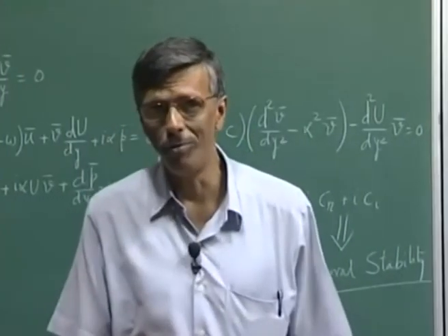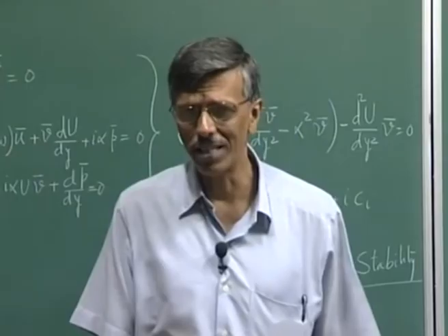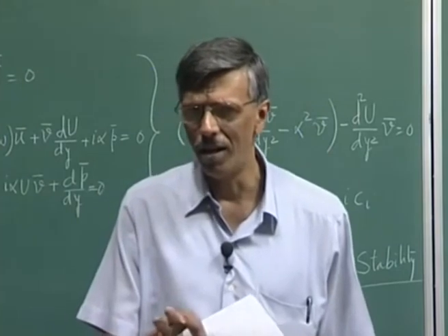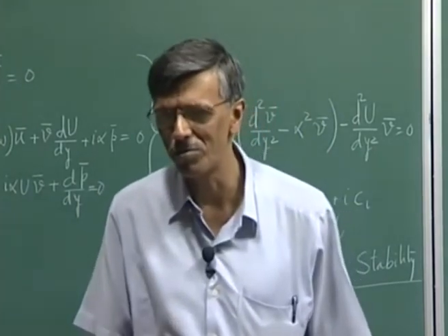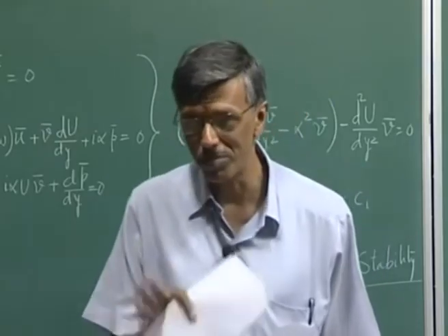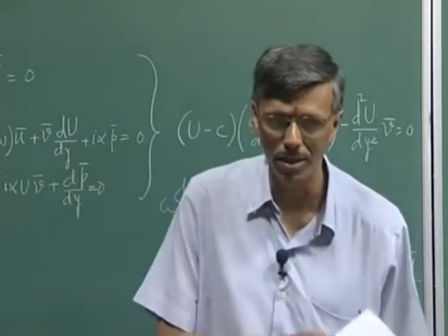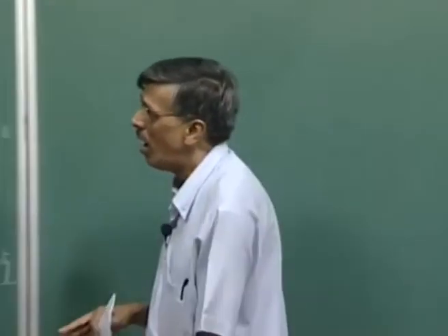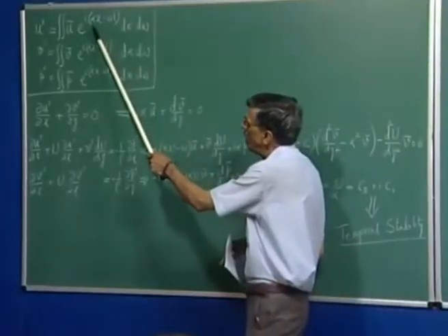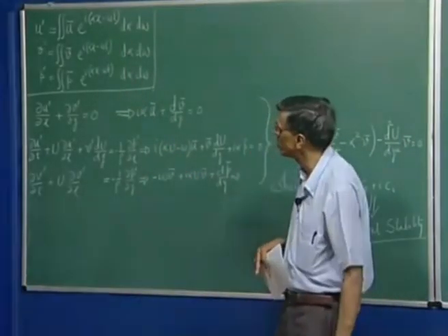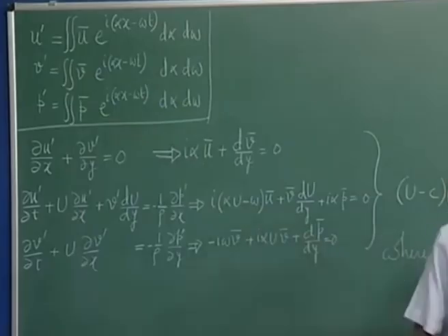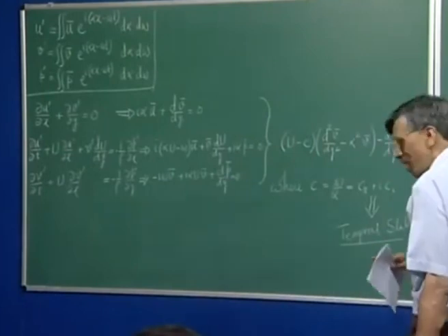For the time being, I will go with the results that are given in most of the books, except the one that we have written recently. We would only talk about downstream propagating disturbance. When it comes to upstream propagation, we will specifically mention it, and you will be aware of it. Okay. So, alpha r is the phase, alpha i determines the stability or instability. For a downstream propagating disturbance, alpha i being negative would be the unstable scenario. Okay, that is about alpha.